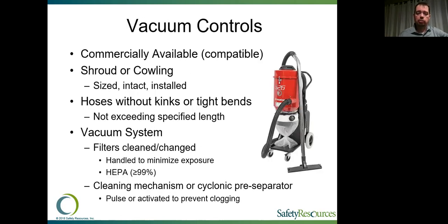Again, this is something where employees need to be able to recognize that if they're performing the work and everything seems to be working appropriately with the vacuum system, but then somehow in the middle of the shift, they're not seeming to collect the dust the same way as it did at the beginning of the shift, work needs to stop, and they need to inspect that system and make sure that the filter has been cleaned, and that there's nothing else that could be causing any type of clogging in that.